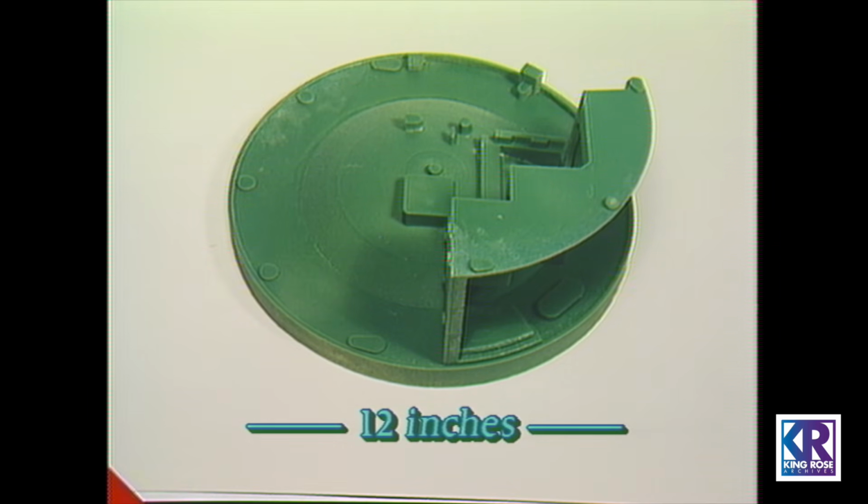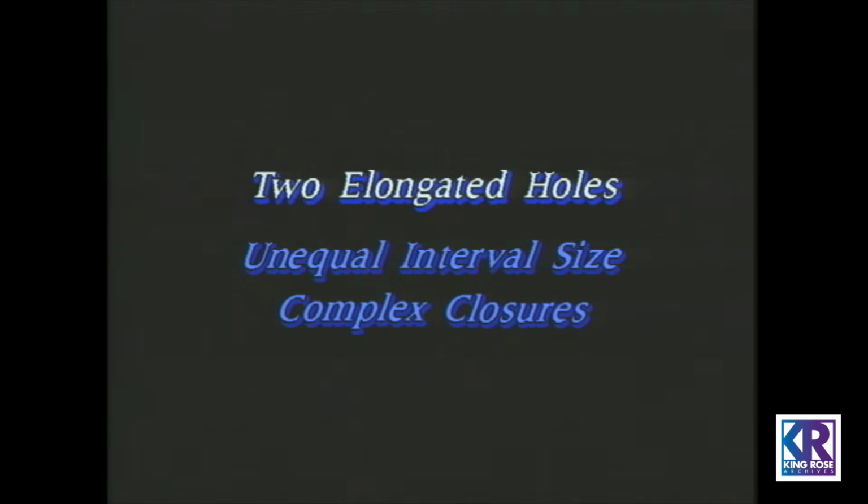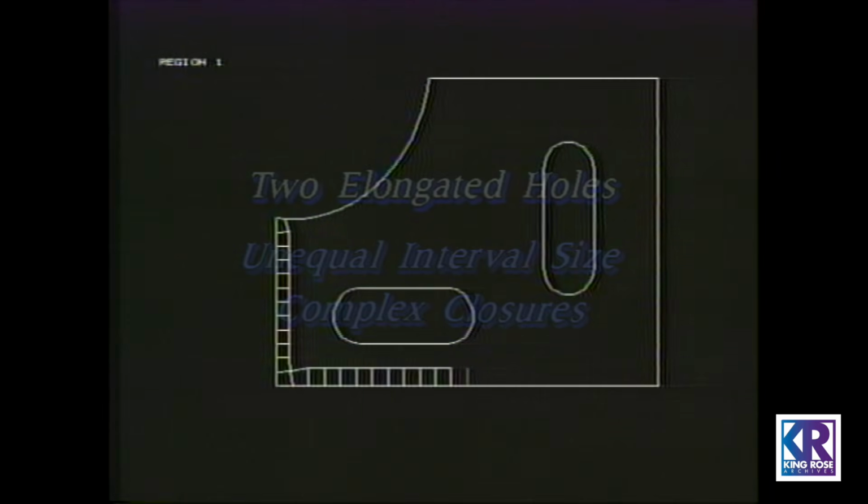FastCast is the development and integration of these technologies into an analysis toolbox to be used with the electronic design. The first step in this toolbox is the creation of a solid model representation of the part. This 3D model of the final object will eventually serve as the electronic data to generate the part by selective laser sintering. To perform analytical computations on the design, the solid model must then be converted to a mesh suitable for finite element modeling, a mathematically correct data file in a form that analysis techniques can use.